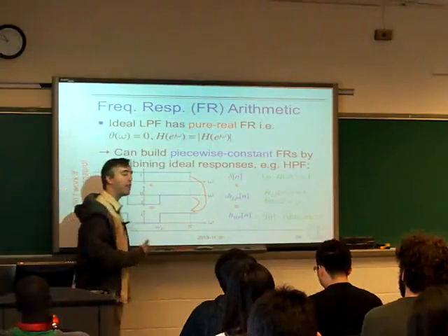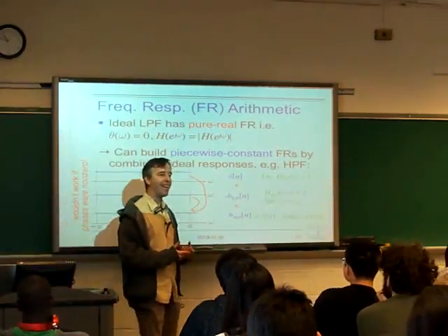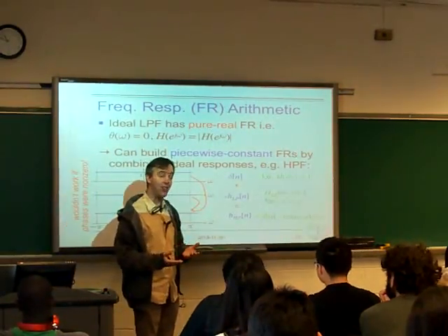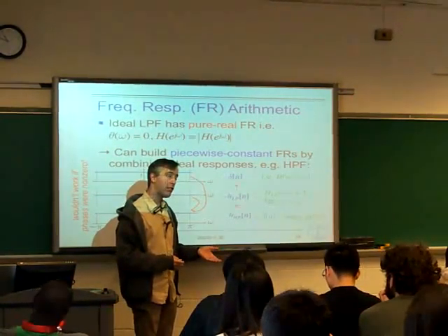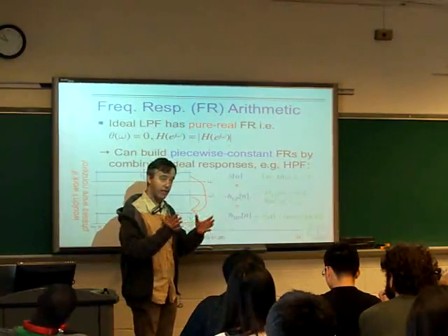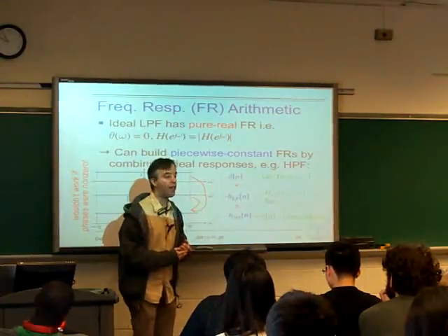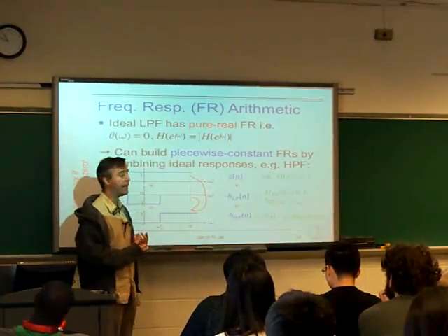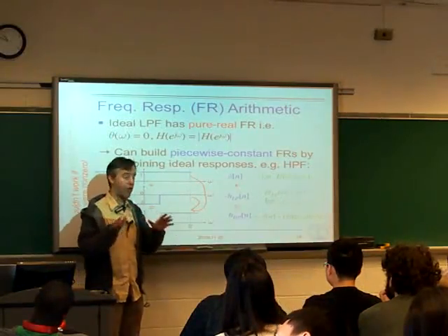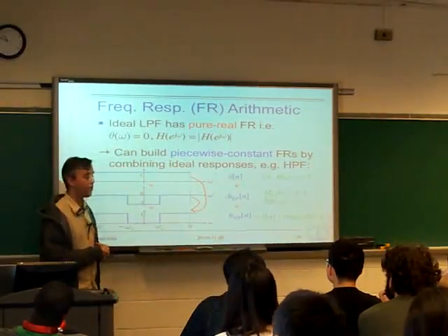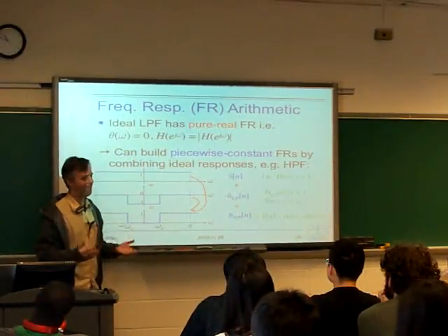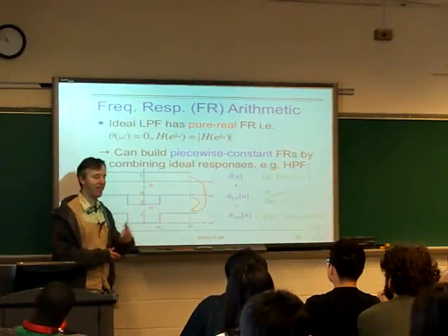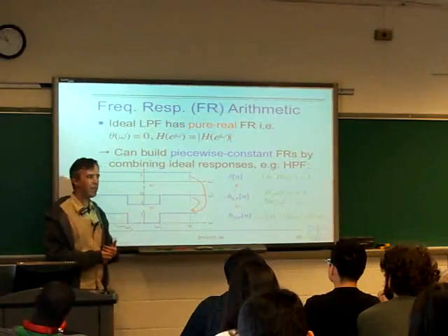one way of building FIR filters, and it's very hands-on. Sort of makes sense, right? That we sort of used our idea of what an ideal impulse response would be, and then we just sort of built an FIR filter out of that by extracting a bit from the middle and trying to smooth it out so we didn't get discontinuities, to try and get it a little bit well-behaved. But it's very ad hoc. It's like following your nose, and it's like, in the end, what did we get?